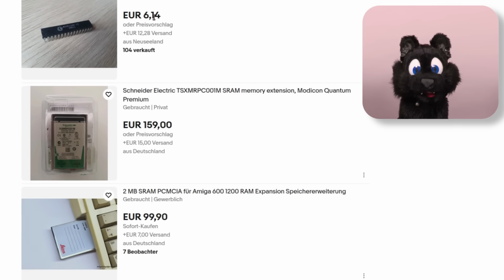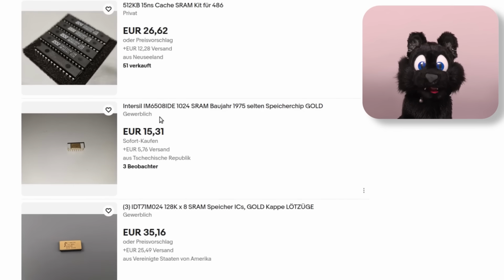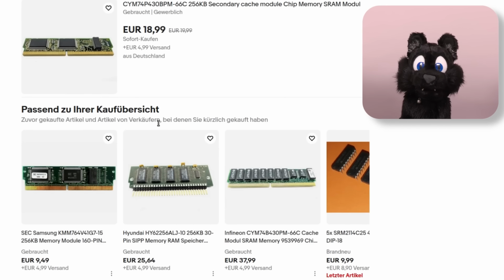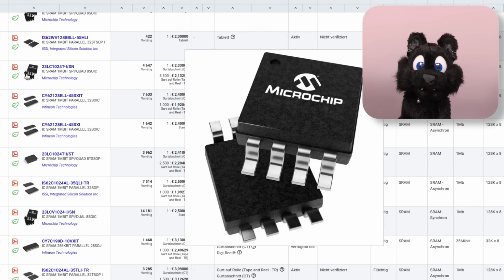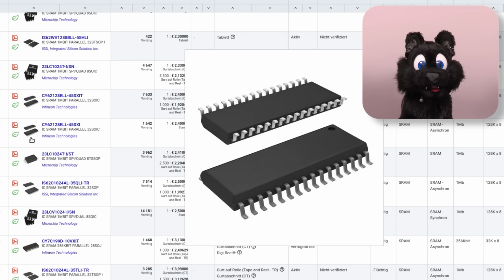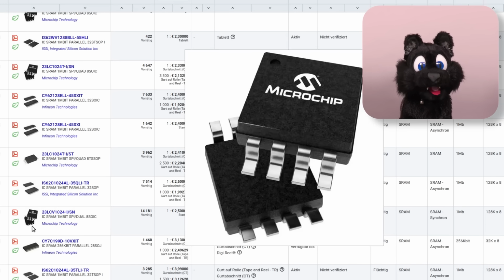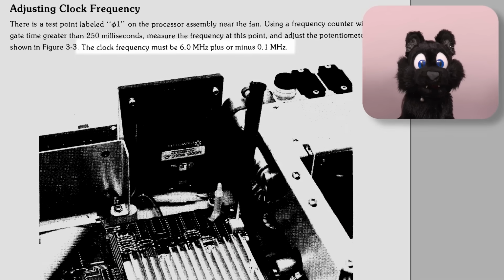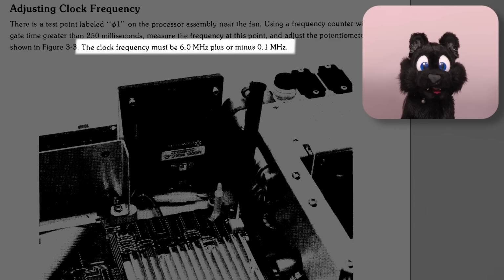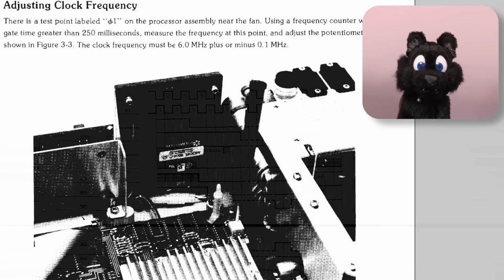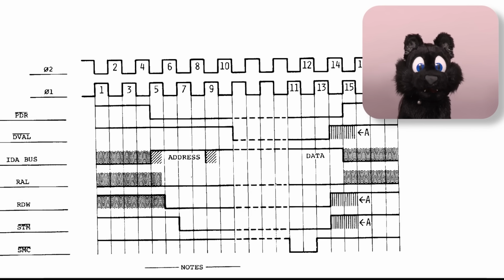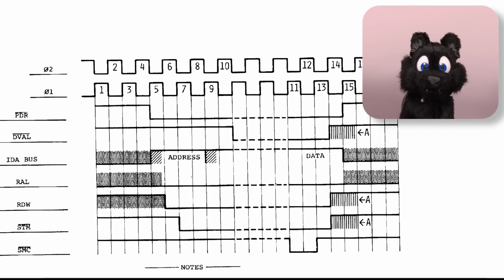I did a quick search on eBay to find dip-cased SRAM chips with parallel bus pins. Those are rare these days. Most new SRAM is either serially connected or surface mounted. Also, the 9825 runs at 6 MHz, so it has to be able to cope with that. A single RAM cycle does have several clock cycles for the bus multiplexing, but the times to enable the output still have to cope with the single clock.